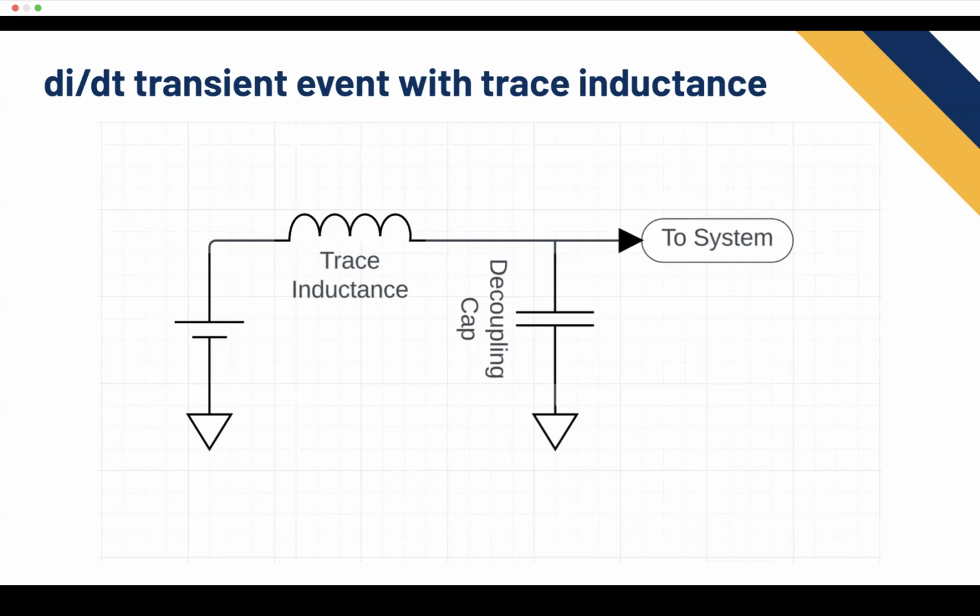This is actually a really big deal for IC packaging because those pins are so small that they can introduce a lot of inductance into the system. So let's say it's a digital IC. Digital ICs have lots of spikes, it's up and down, right? Because it's zeros and ones. So they actually have very spiky waveforms on their power rails.